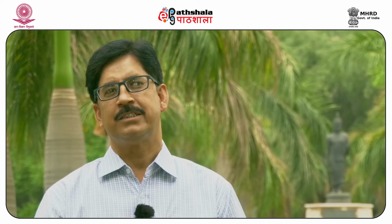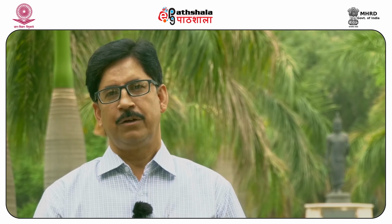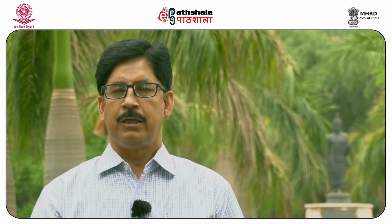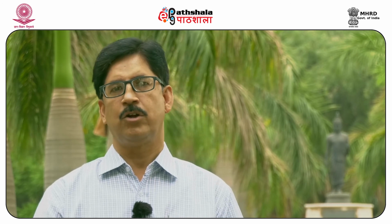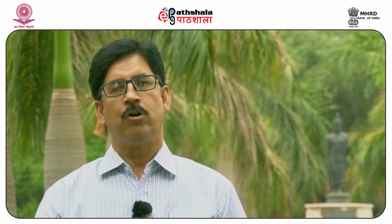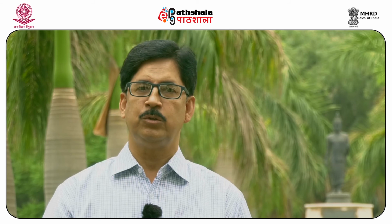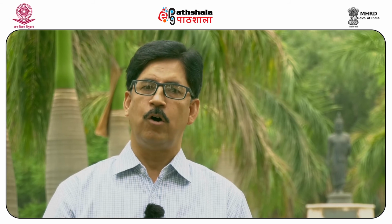To summarize the deformation structures and their importance in civil engineering constructions, we have seen contacts, primary structures and deformation structures. The primary structures are the layering in different types of rocks, from lamination, foliation plane and bedding plane to flowage plane. Then we have contacts, which are between two different rocks, and then some important deformation structures. The most important ones are joints and shear zones, followed by faults and folds.